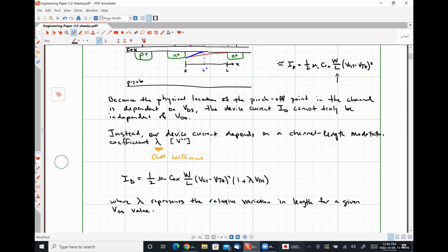We're typically going to overestimate the effects of channel length modulation in our designs, even if we have longer length devices, just because of it being a constant value effectively for that process run, where it's really only truly representative of the smallest size of transistor that you're expected to implement in there. All right, so channel length modulation is going to play a big role in our small signal model that we're going to talk about in a couple of minutes. But before we do that, we're talking about transconductance.